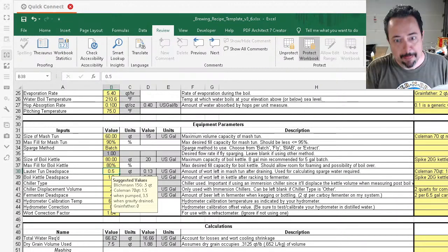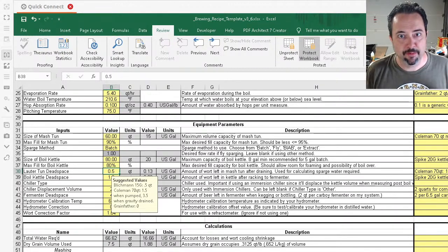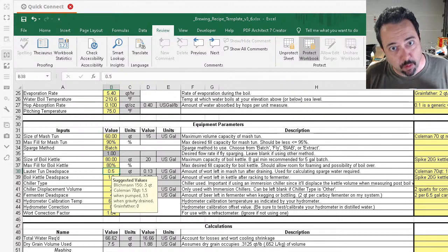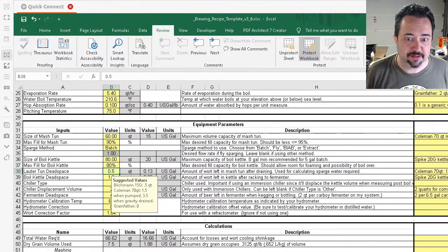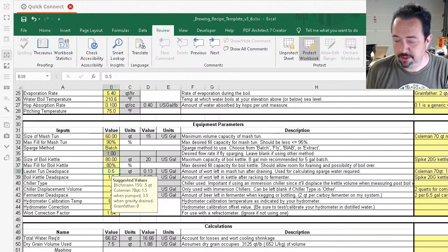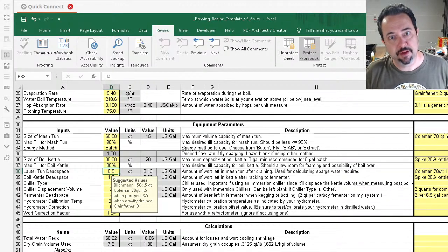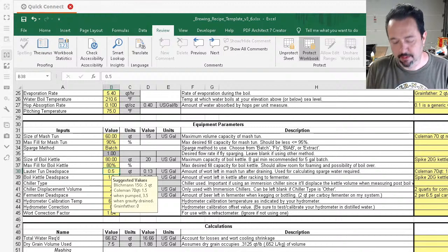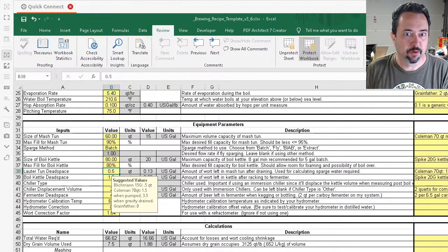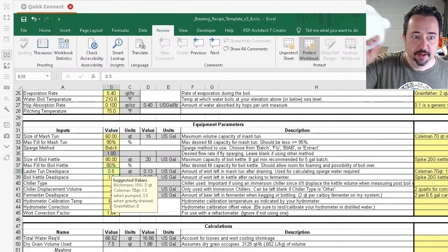So yes, I'm that anal about it. You don't really need to be that anal, but water volume does change with temperature. So I would suggest staying with temperatures that are in the range of what you're going to have at the end of your measurement. But I would just add the water in there, drain it, take that water that's still sloshing around in the bottom of your vessel, and use a funnel or pour it into a bucket or something and measure it in something.